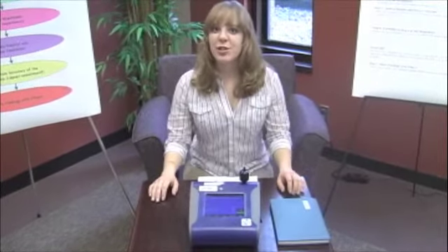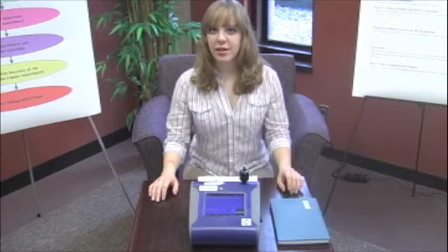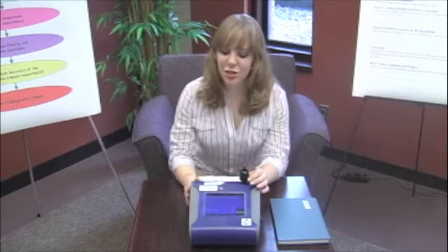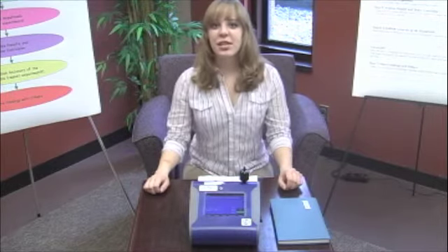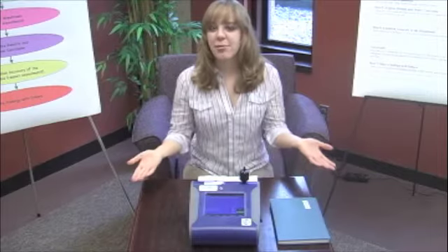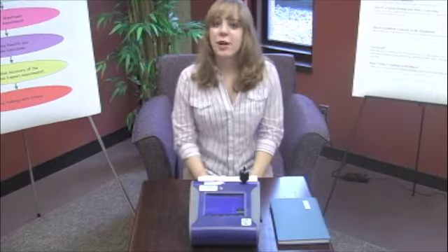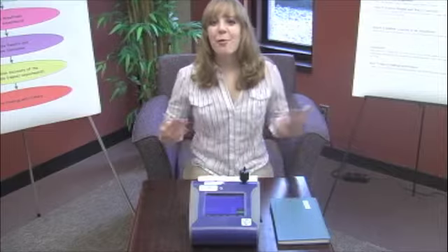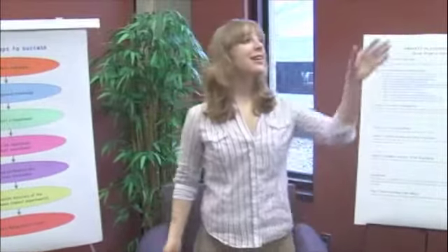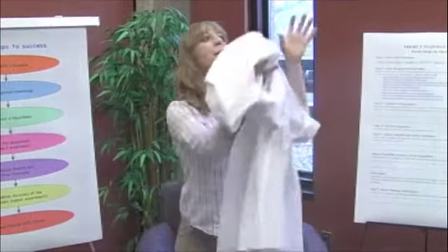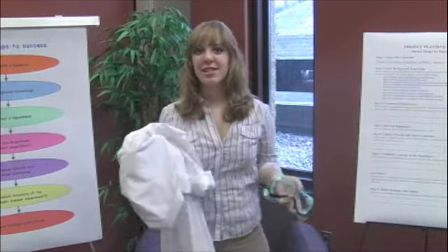In this experiment, we chose to study PM2.5. So, I chose the nozzle that measures particulates 2.5 microns and smaller. PM2.5 is of concern because particles of this size have the ability to bypass the body's defenses and travel deep into the lungs. Before conducting any real experiment, I always remember to put on my lab coat and goggles, because as you know from your own experiments, safety first.